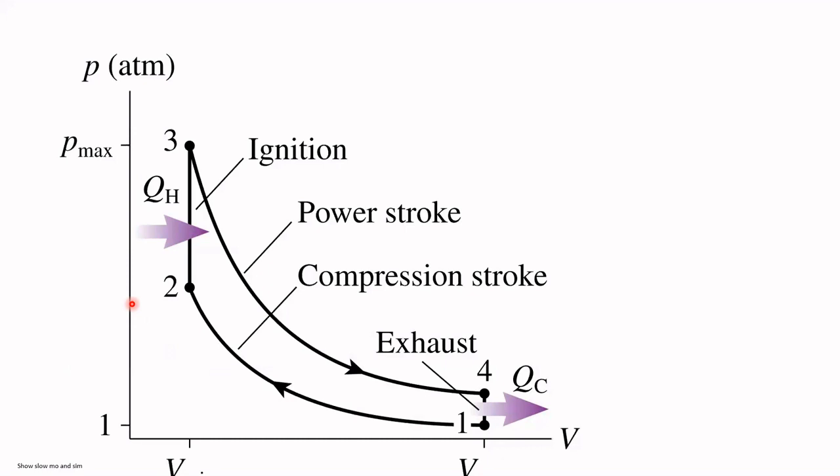So it's definitely a good approximation to call that an adiabatic process. And then similarly, the power stroke, this is where you actually extract the useful work from the gas. When that super hot gas that's been heated by the combustion of the fuel is allowed to expand back out to its initial volume, and I'm realizing I can't see the subscripts V min and V max. That might be a problem. This is supposed to say V min, and this is supposed to say V max up here.